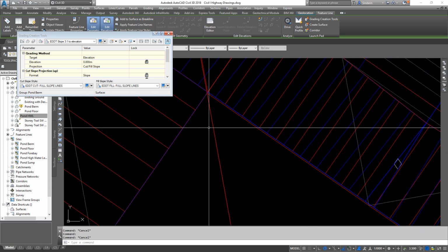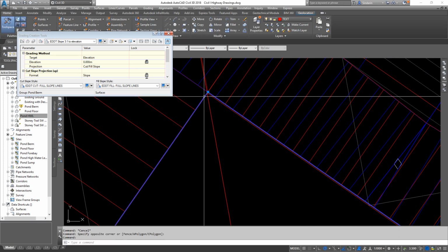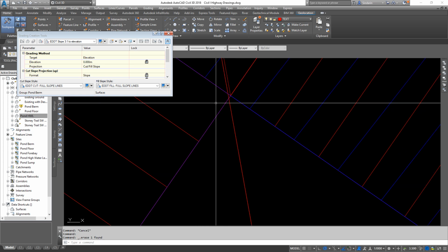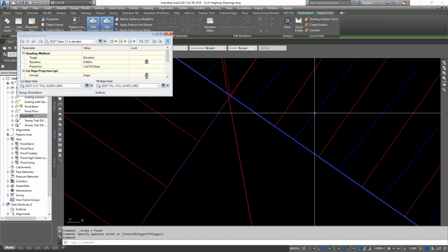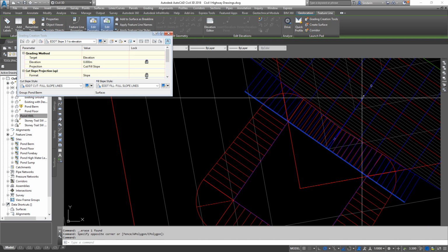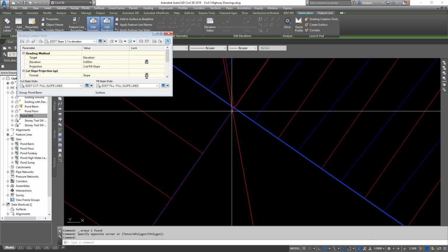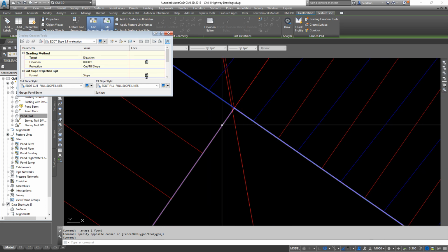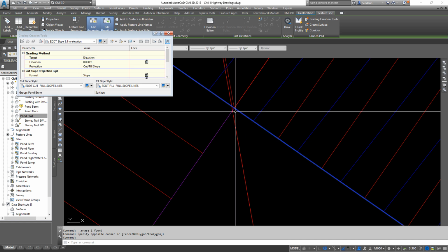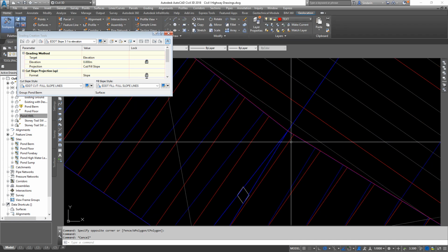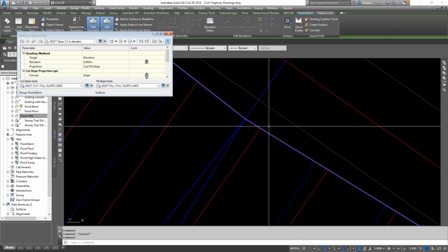And it looks like that's moved. Or no, that's just our red line underneath, so we can delete that. So we've got our 1114.509 reading off the berm, 3:1 down. We've taken our 1114.509 sump feature line and just snapped it to that blue line, perpendicular. So things should more or less